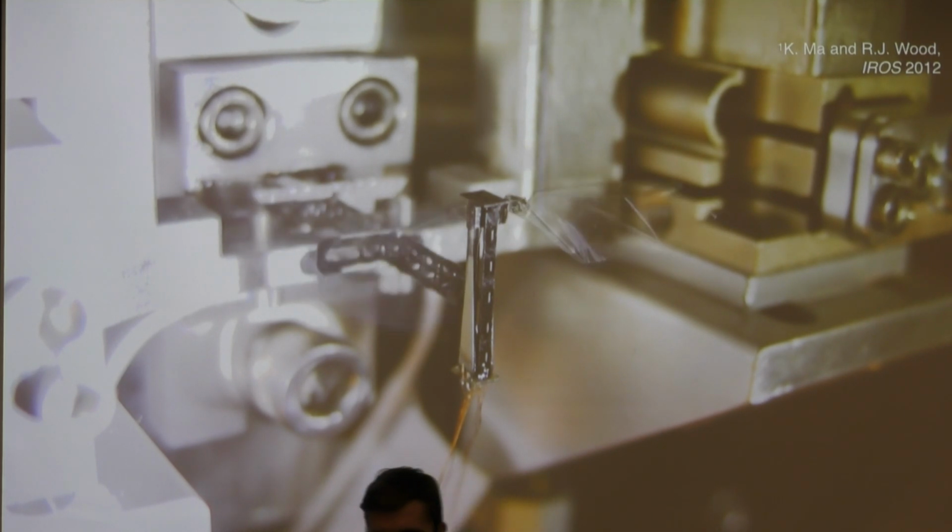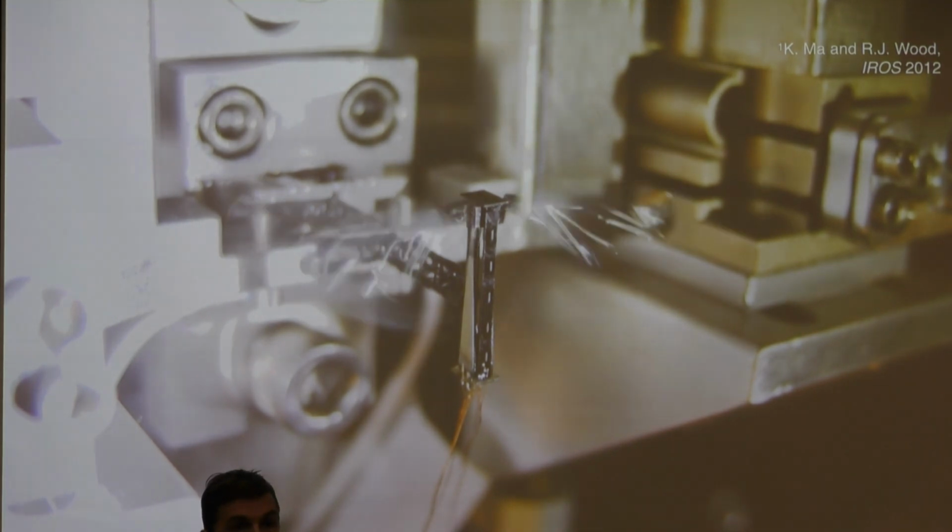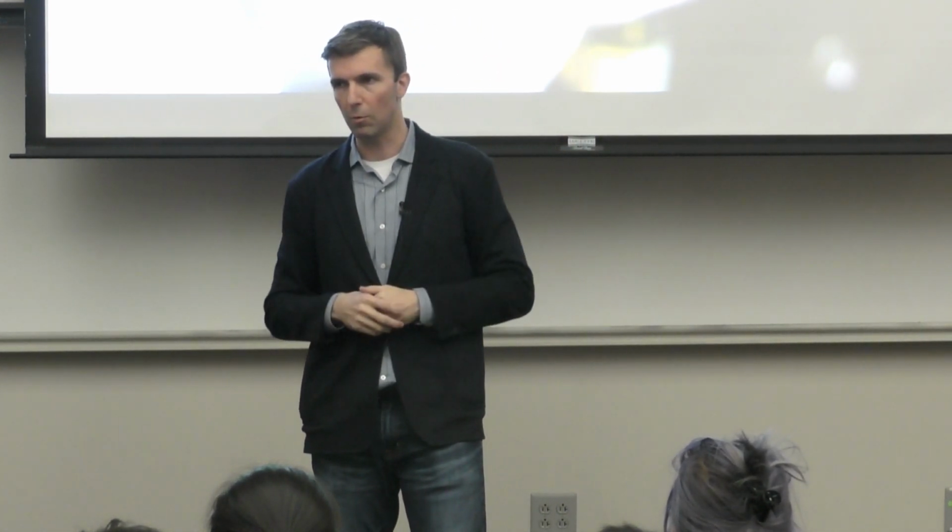The other thing that's being illustrated here is we split the robot into 2 halves, and we actuate each half independently, and so we can achieve what we call roll by doing amplitude modulation on one side with respect to the other. So for a fixed frequency, if we have a greater amplitude, we have a greater velocity, the lift roughly goes as velocity squared, and so we can get greater lift on one side than the other, and we produce what we call a roll.